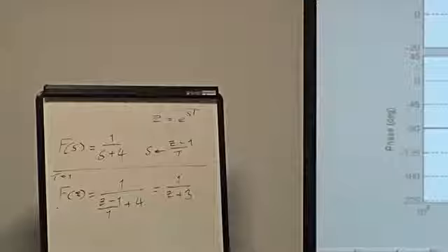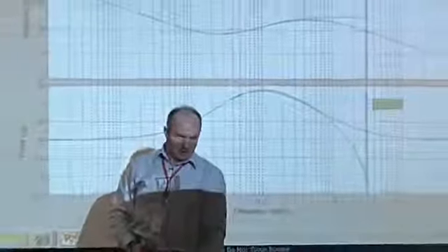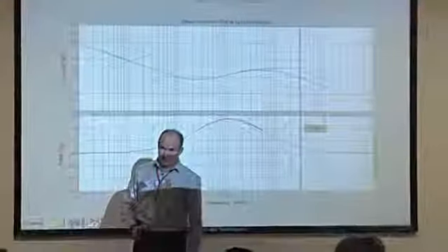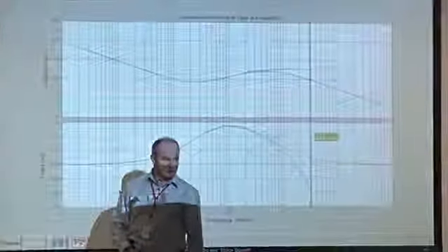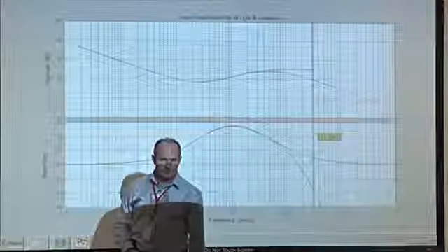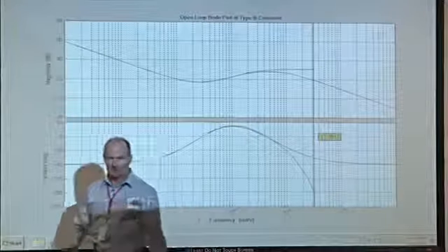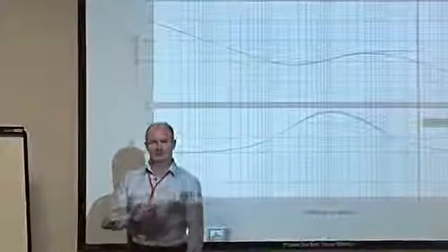That is the z transform of that transfer function for a sample period of 1 Hertz. Now there's a problem with that. Can anybody see what the problem is? Somebody saw it. I know you did. I didn't catch all the words. If the word unstable was on anybody's lips, that's absolutely right.